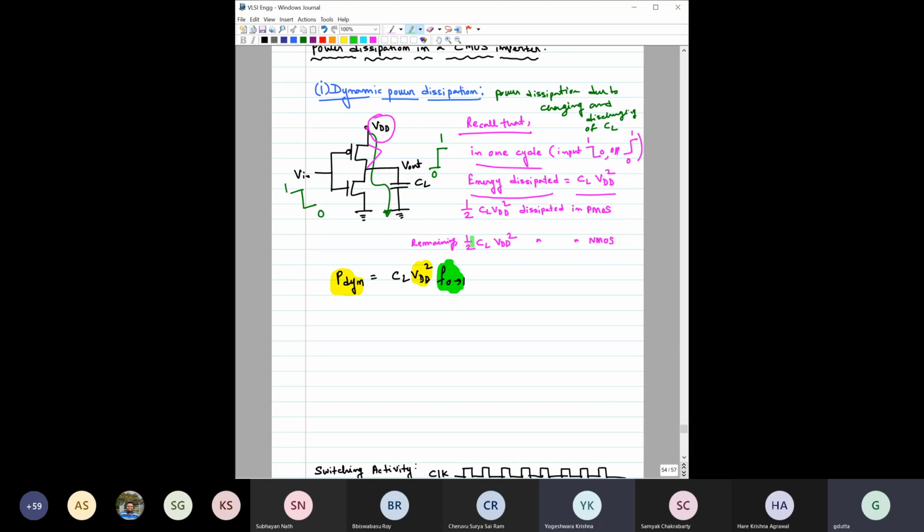And the clock frequency increases from one technology node to another, because when you shrink the device, you reduce the delay in the device, so the device can be operated in a much faster fashion. So you can further increase the clock, but when you do, see what is happening: the dynamic power dissipation is also directly proportional to this frequency.